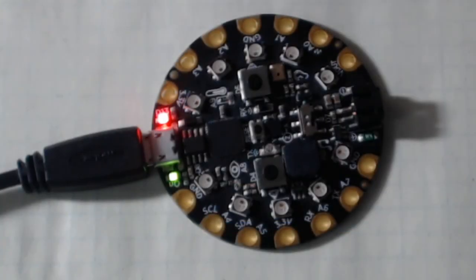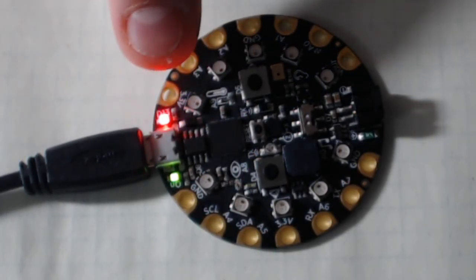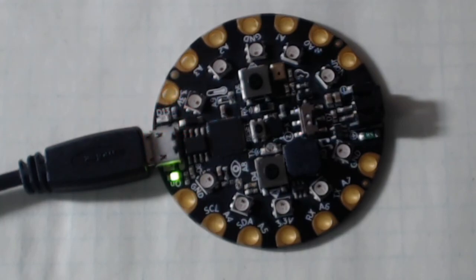If you notice over here, we have an LED D13. That LED is flashing now. It should be on for 100 milliseconds and off for an additional 100 milliseconds, meaning the cycle is about 200 milliseconds or 0.2 of a second. So let's go ahead and extend this. Instead of 100, I'm simply going to change in my code to 500 and upload this to the board again. This will take just a minute.